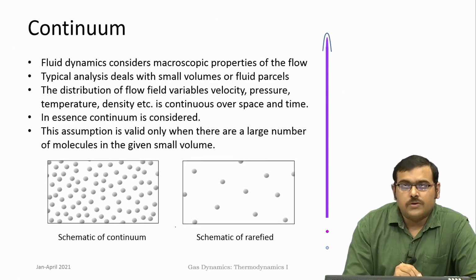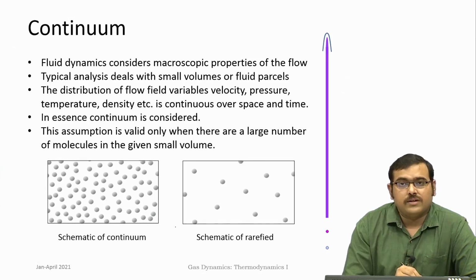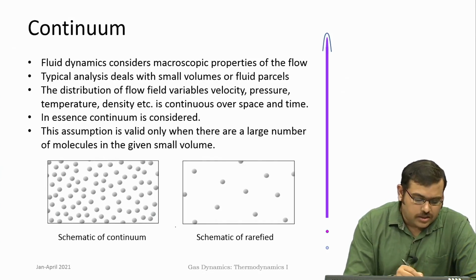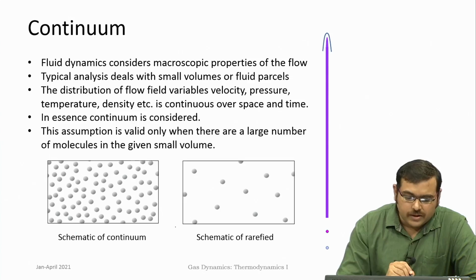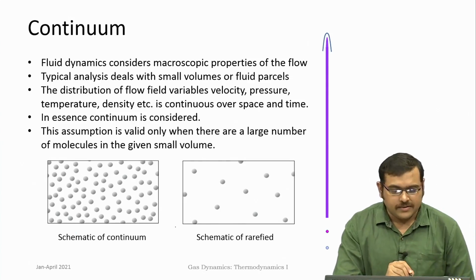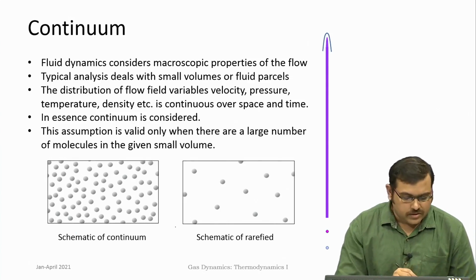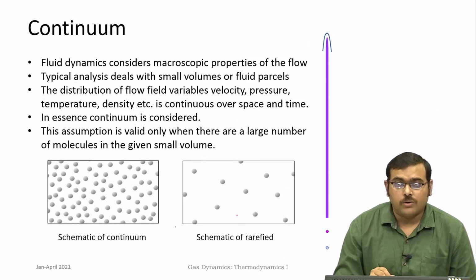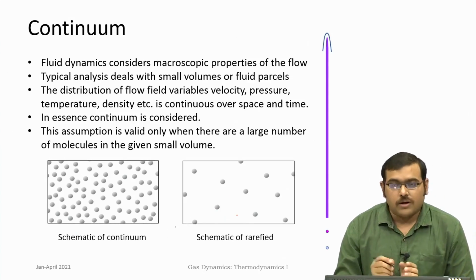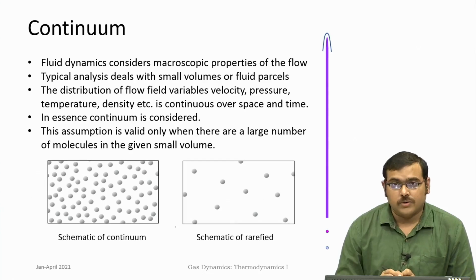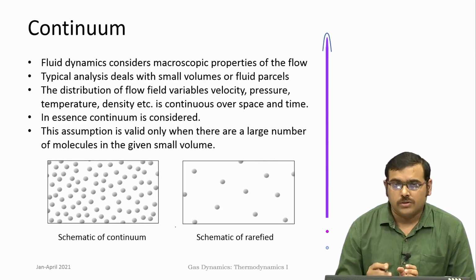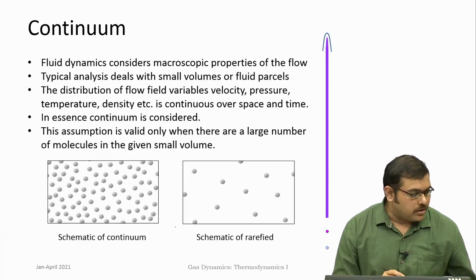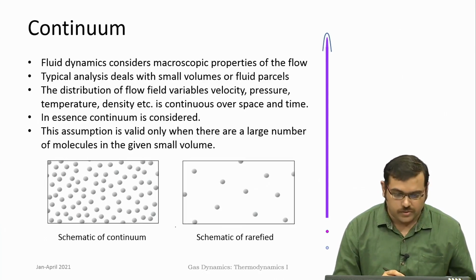But this view is valid only if there is a significantly large number of molecules in the given small volume that you have considered to analyze the fluid flow. If that does not hold good, then you are not in the region of continuum, and you will have to look at other methods to describe the movement of these molecules.